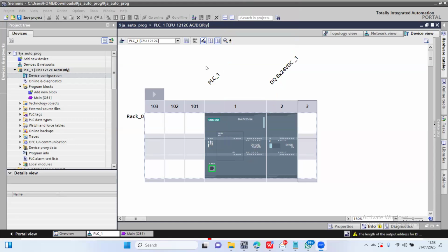It's not too different, to be honest. If you know how to write a simple program in Siemens, once you understand the environment, like let's say I try to write the same thing in Rockwell, the first thing is, how do I connect to this PLC? You learn how to connect to the PLC. With Siemens, you program within TIA Portal. With Rockwell, you may need to use RSLinx or FactoryTalk Linx. You use that to connect to your PLC.